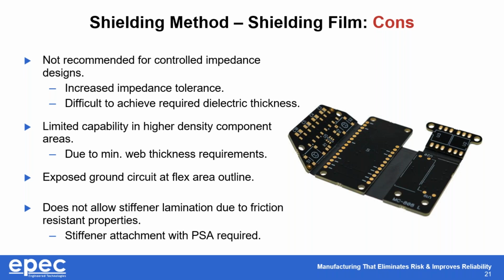It has some limited capabilities in higher density component areas due to the minimum web thickness requirements of the material. If you try to go below what the material can support, those webs will break and cause parts to get scrapped out.